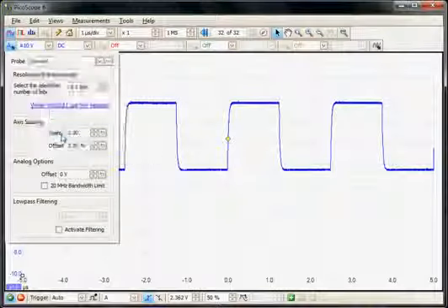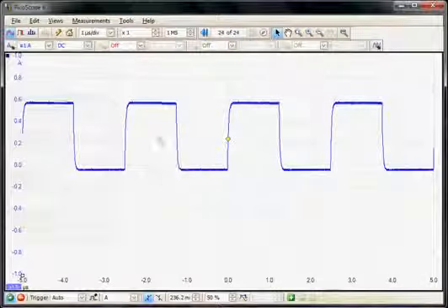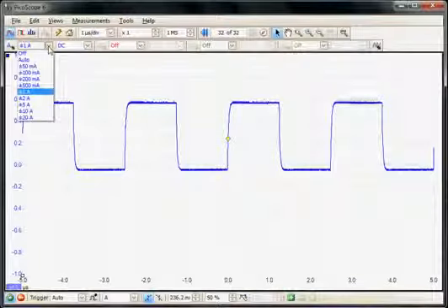So we could again select our current probe, and here it's automatically then changed the range to amps as we defined, and it's plus or minus 1 amp. But we can see also all the vertical factors have been changed correct for amps.